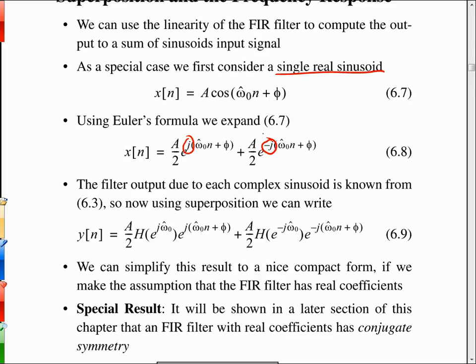And we know from our frequency response analysis and definitions from Monday that the individual responses to each of those complex sinusoids can be obtained just by saying, if this is the input, magnitude and phase, it comes through to the output at the same magnitude, with the same phase and the same frequency, but then it's also picking up the frequency response at that frequency omega naught hat. That makes sense? Remember, a sinusoid goes in.